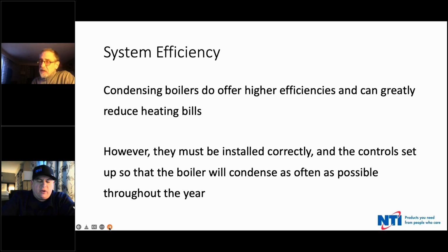Well, just figure on startup, the circulator alone has to increase the amp rating to move the water through there, because now, let's say you didn't flush your system out and you get sediment in there. So I'm just saying, like you said before, cruise control is the way to go. Yeah, and steady state. So ideally, you're utilizing both turn down and reset to maximize the efficiency of the equipment and the longevity of the equipment.